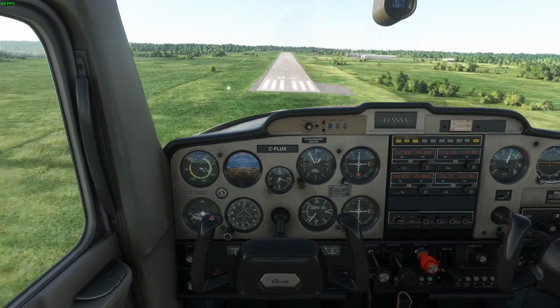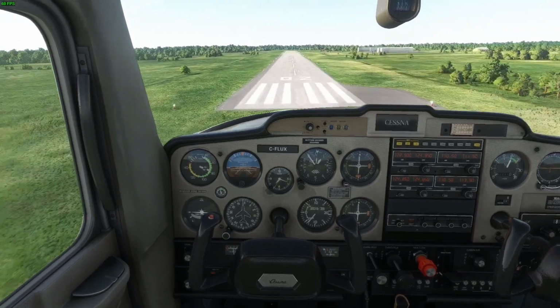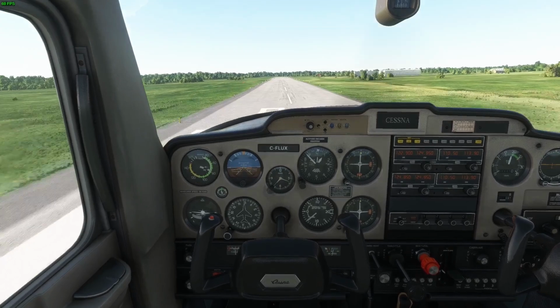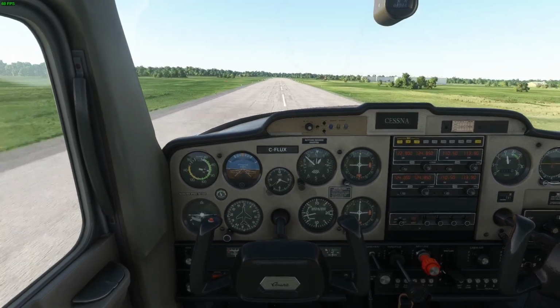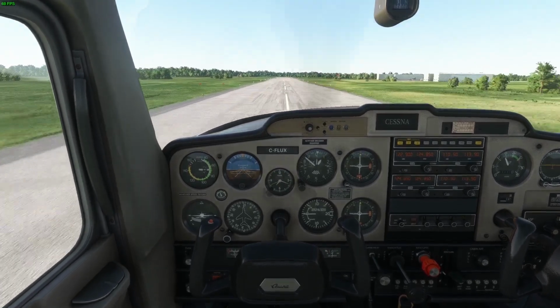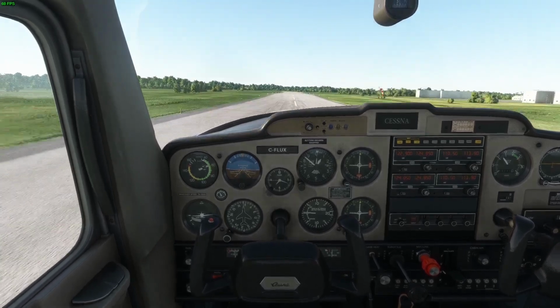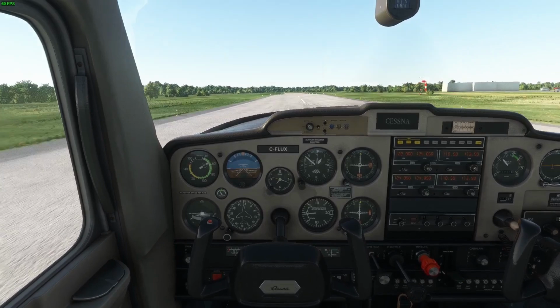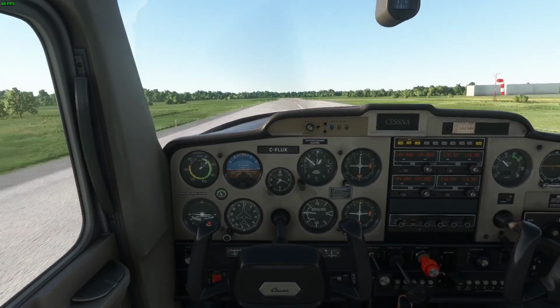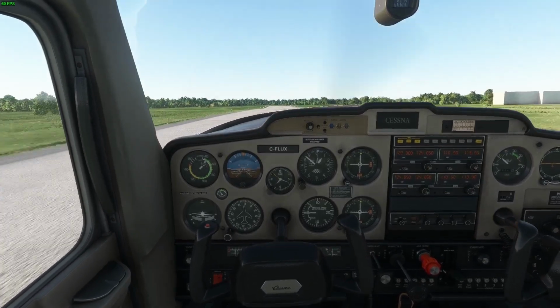Once you're down there, slowly pull the power to 0 and pull the plane up level to the ground. Keep it level. As you lose airspeed, the nose will want to drop. Don't let it. So as you slow down, gradually pull back, but don't balloon up. Keep it level, level, level, and the plane will land when it wants to.